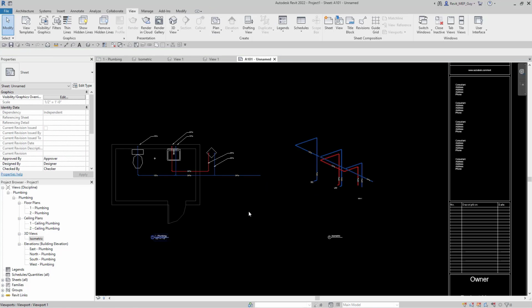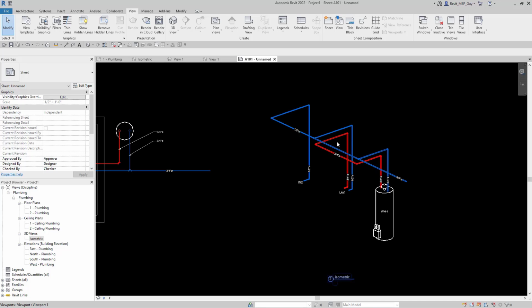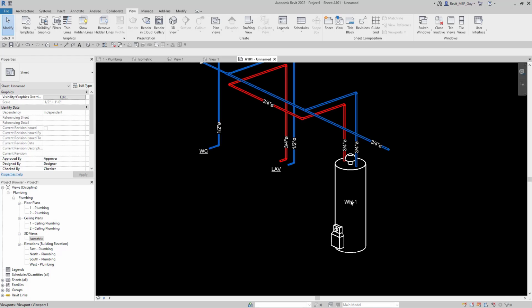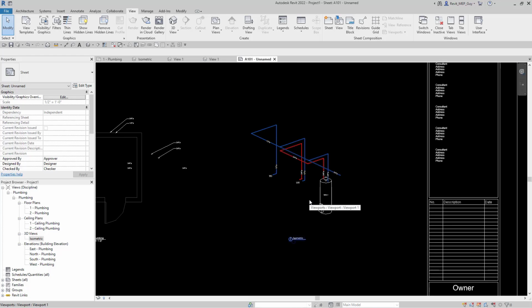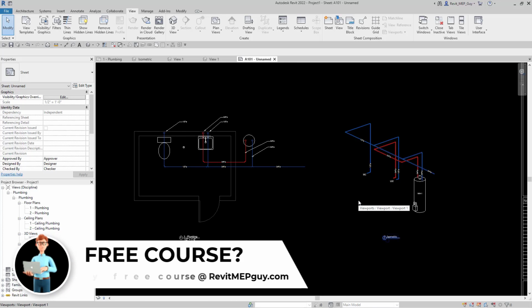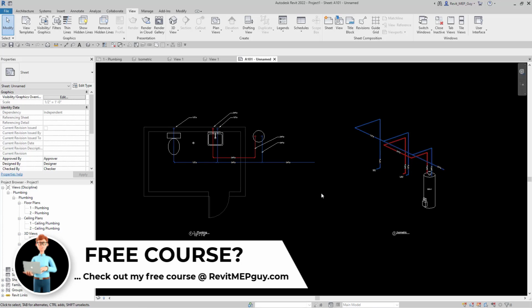So that's how you create a basic plumbing design. Calculate your pipe sizes automatically, control your fixture visibility, set up systems, and set up a quick riser. Tag your riser with pipe sizes and use text tags, and also use regular equipment tags to create these simple plumbing drawings.